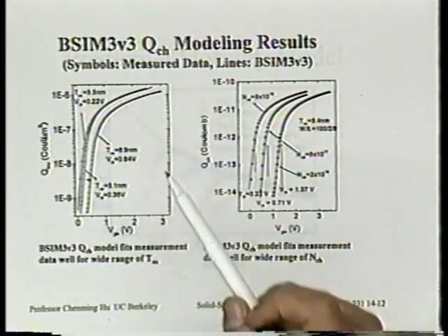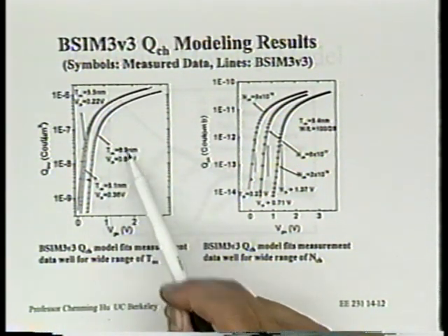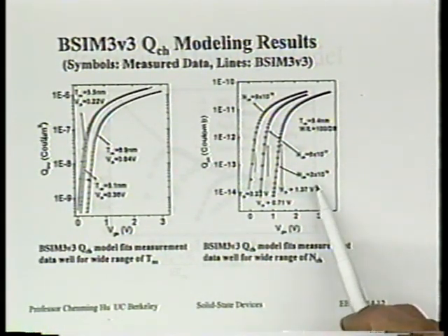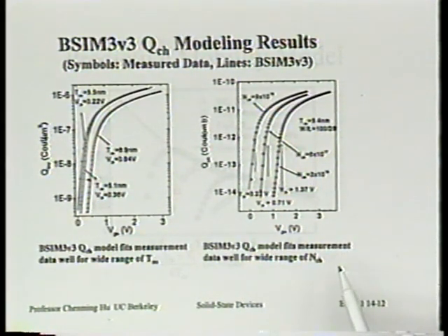Certainly, you will always want to change certain things like oxide thickness. Here we have several oxide thicknesses, 50 angstrom, 70 angstrom. And you change the doping concentration, 6E17, all the way to E18s. And of course, we also change the body bias and all those sorts of things. That's how you test this. But when you pick a quantity like comparing this against just Q inversion, ultimately we're interested in some sort of ID, and more specifically, with a smoothing function, some small signal quantity like the gradient of the current. So I will show you that.